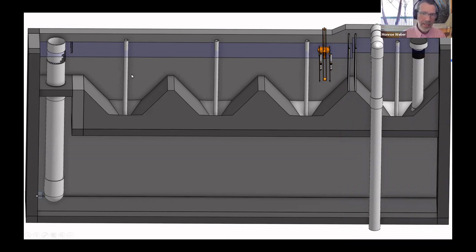And the way that the grit is handled is it's going to drop into these hoppers, and if the hopper begins to fill up, the plant operator can grab a hold of this 2-inch diameter PVC pipe and pull it up. That unplugs it from the socket that's embedded in the concrete in the bottom of this hopper.